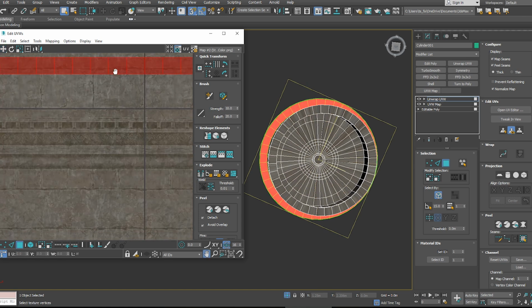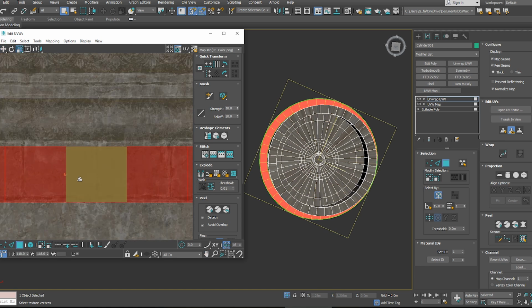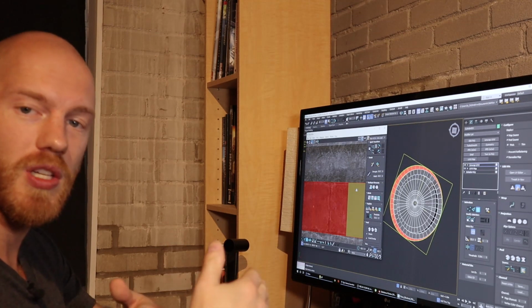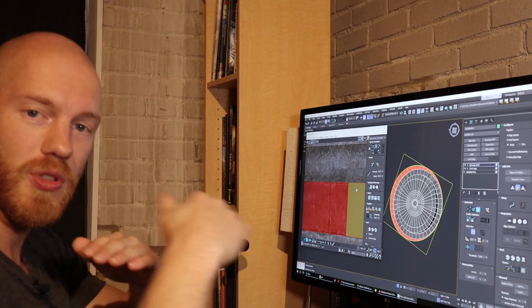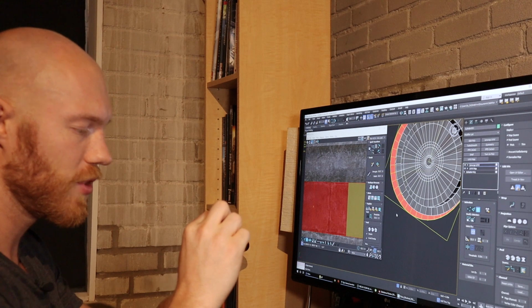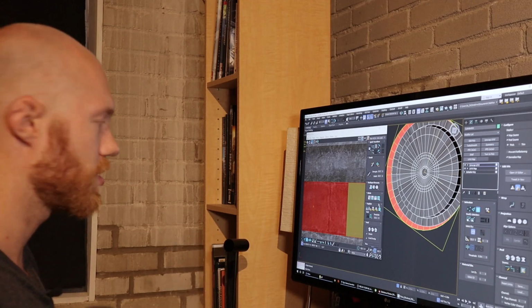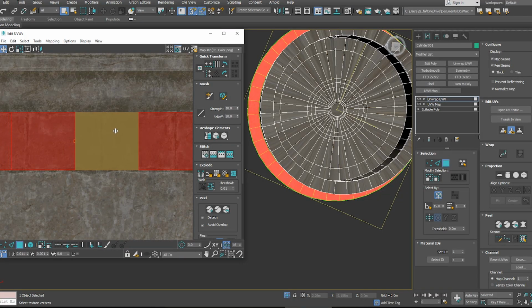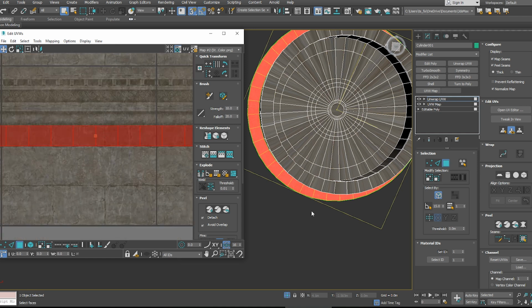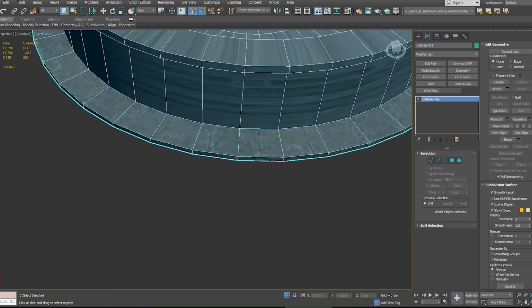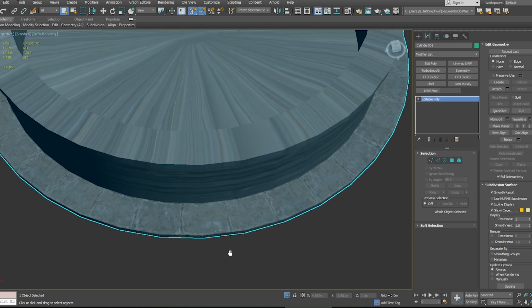And then I just would move this into place and scale the strip a little around till it's lining up with these horizontal grooves for these bricks. Because remember, you want the edges of your polygons to align with the edges in between your trim strips. And that way you'll get that nice chunky, damaged edge that flows around your mesh really nicely, like I showed in the first trim texture tutorial. Something like that. And then I just collapse all. And you can see now it's perfectly UV'd to that strip.